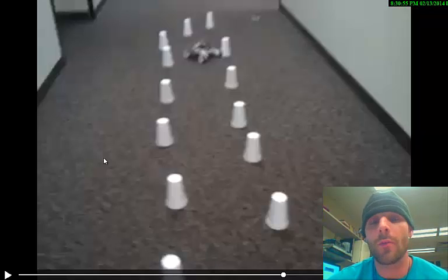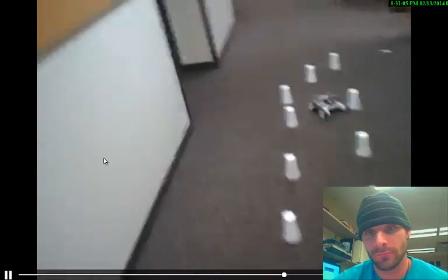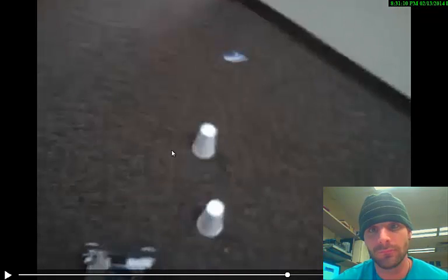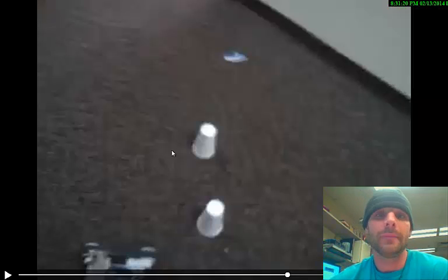Localization is just for the robot to know where he's at on an XY plane, or if you're doing something three-dimensional, for the robot to know at any given time where he's at on an XYZ plane relative to his starting position, so that he can figure out, hey, where am I at, so he can work on building the map. So localization is very important in map building robots, because if your robot is not consciously aware of where he or she is on an XY or XYZ coordinate system, then whenever he does a scan and he gets more information for his map, he has no real way to know where that information goes relative to his last scan.